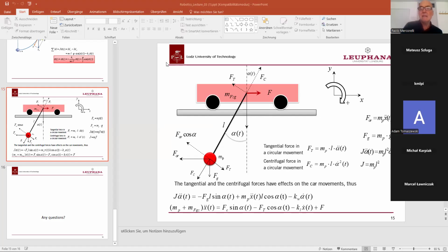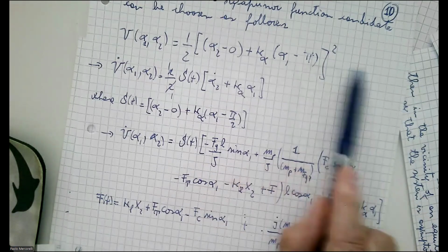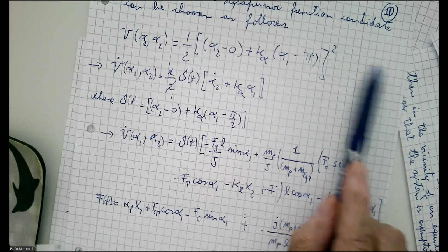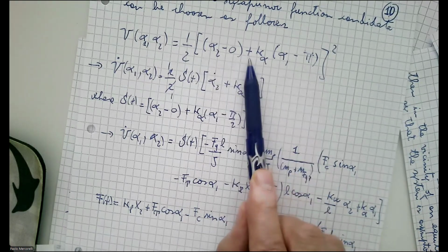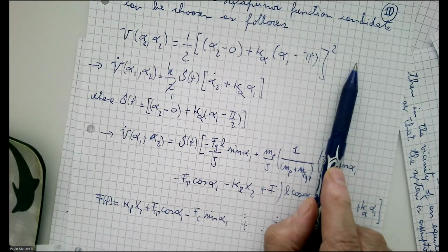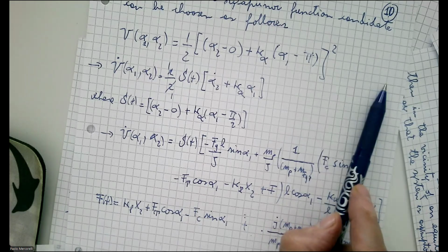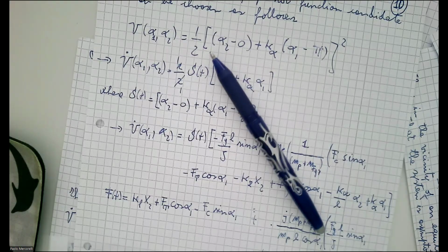This means we calculate with the second Lyapunov function, which is not exactly a Lyapunov function because the function does not contain all states. If we neglect x1 and x2, we try to stabilize this equilibrium point independent of x1 and x2, which could be any value. In particular, practically, we will run far away from the origin.